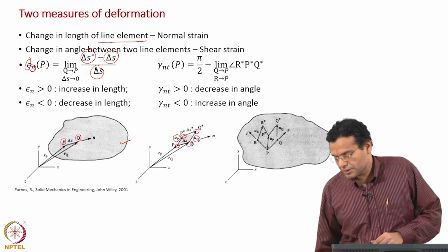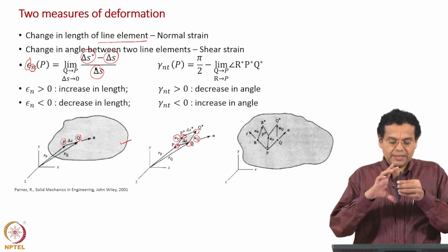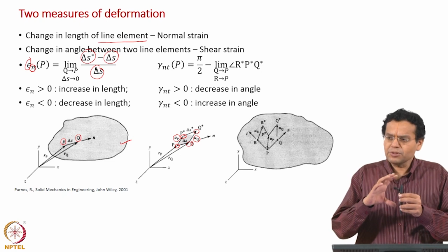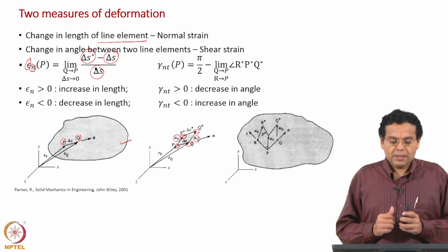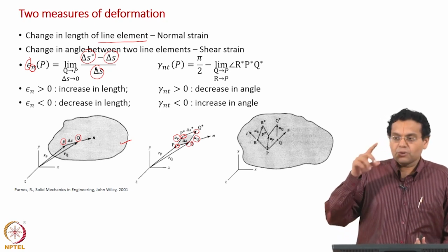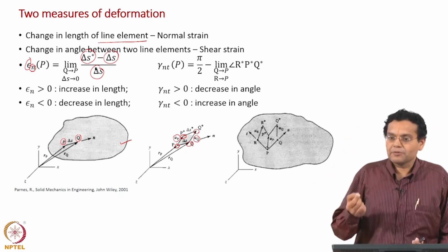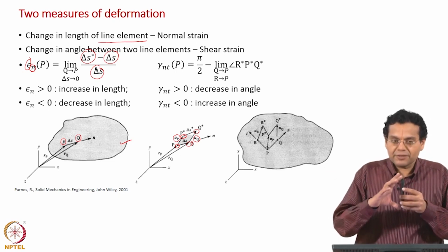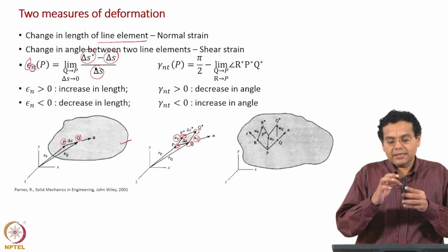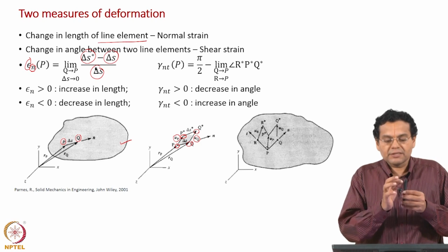What you usually know is that you took the original length and the final length, took the difference, and divided by the original length. This gives you the normal strain averaged over the entire length of the rod or thread. But remember, we are going back to our linear momentum balance, and all of that is valid at every point. So, we need a point form of strain. What you know is the definition of average strain. If there is variation of strain along the length of the rod, then we need a definition of normal strain which is valid at every point.